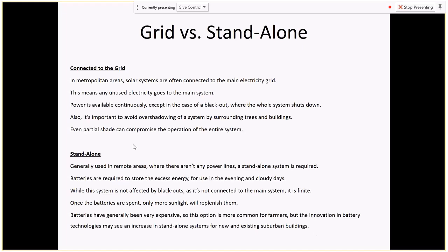Another thing, and we don't have that in here, is probably the hybrid of those two, which is a grid-connected battery system. And it's probably what, once batteries get cheap enough, we'll probably start seeing a lot of those systems about. And if I were to be putting in a solar panel array at the moment with an inverter, I'd want to have an inverter that can be used for battery storage as well as grid connection to future-proof that.